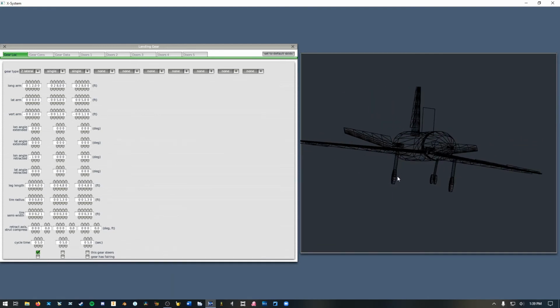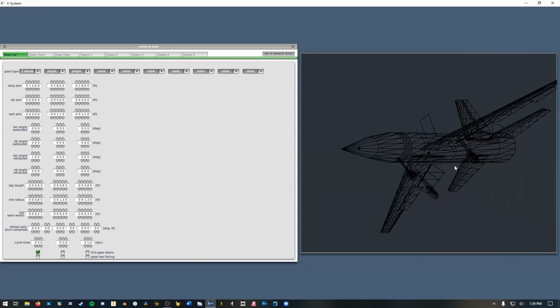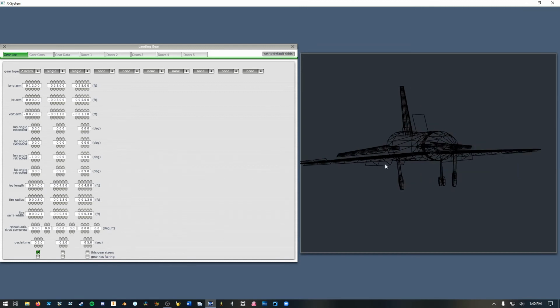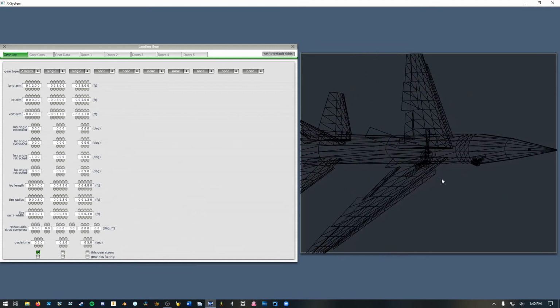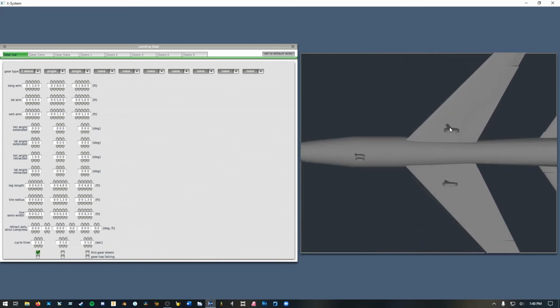And so now for these landing gear, I want to give them lateral degree values for their retraction. So I am going to say this one retracts to negative 90, positive 90, and this gear retracts to negative 90. Now you can see for these they are retracting, but they are colliding with each other inside the fuselage, and they're not fully hidden from view.